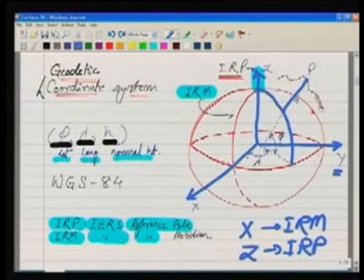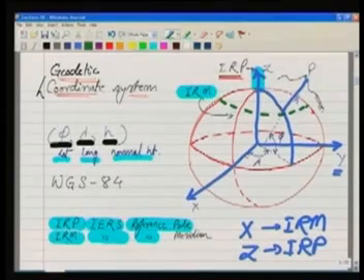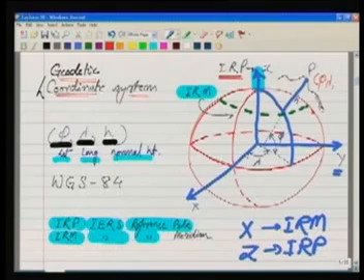At the same time, for this particular point P, the foot of it, I can draw a latitude here. So this angle is the latitude. So this particular point, the foot of the perpendicular, is being defined now in terms of phi, latitude, and lambda, longitude, and the coordinates of point P can be written as phi, lambda, and h.